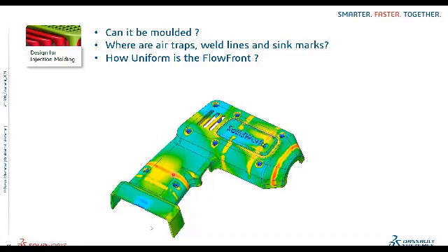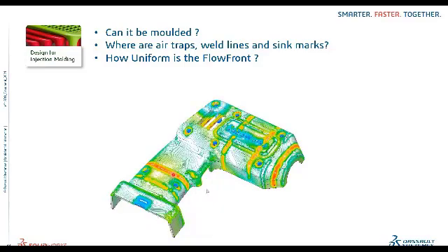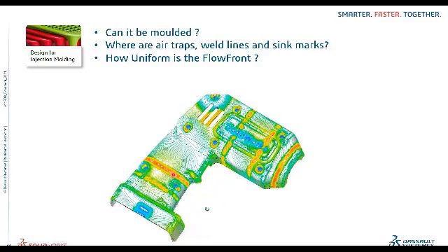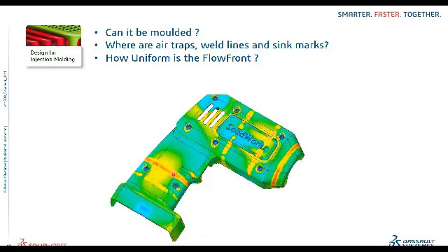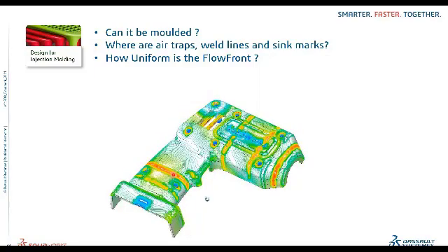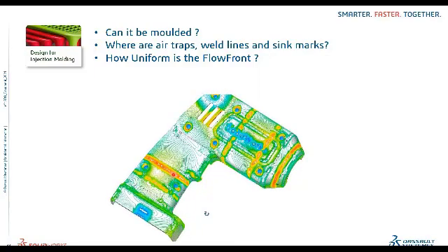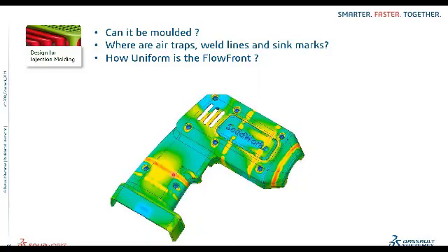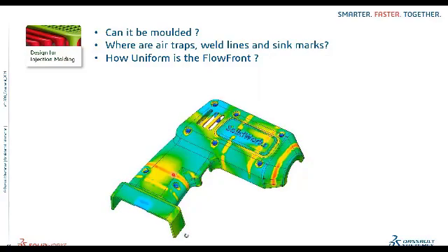So here are the sink marks. If there are any thick edges or thick parts of the component, there we will see additional deposition of the plastic material, which will not provide a proper aesthetic look. At the same time, since there will be a lot of cooling time and the fill time also increases drastically, it is not at all viable or suitable for the commercial purpose of our plastic model.